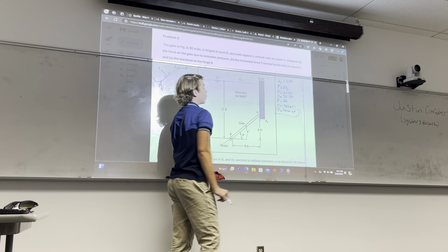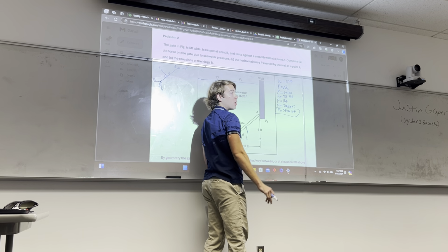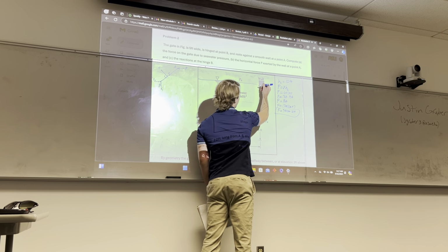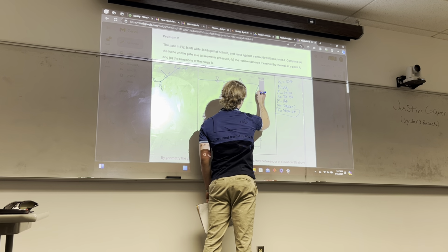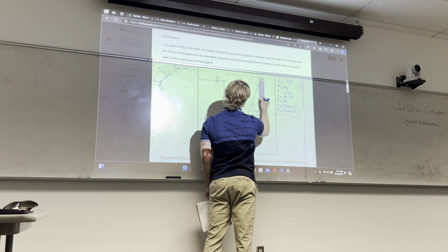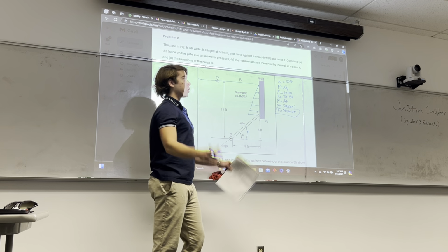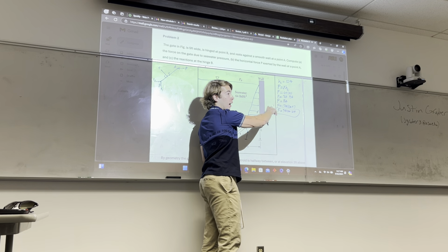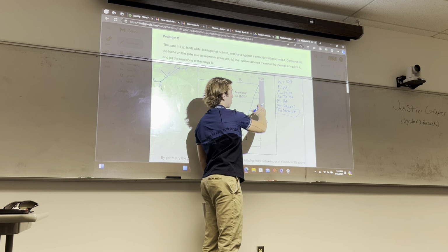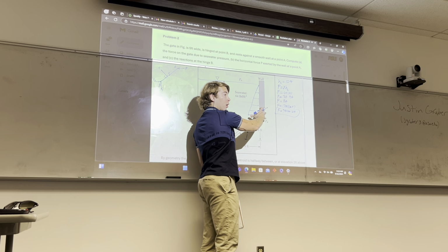Just for reference, I'm going to explain it in terms of using this wall. Since we're assuming density is constant, the water pressure is a triangular distributed load, so we've got forces like that. To calculate the total overall force, it's half of a square. But where this force is acting is going to be slightly lower because it's a distributed load.